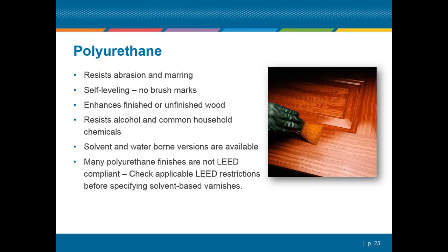The reason I mentioned sanding in between coats is, again, to get to that smoothness and get to that level where we don't have any imperfections in the wood. It's really important to sand with a relatively fine sandpaper. We can get down into the 220 range. The sandpaper goes to extremely fine finishes, but just enough to take any imperfections off the surface and give us just a little bit of surface profile for the next coat of polyurethane to go on top of.